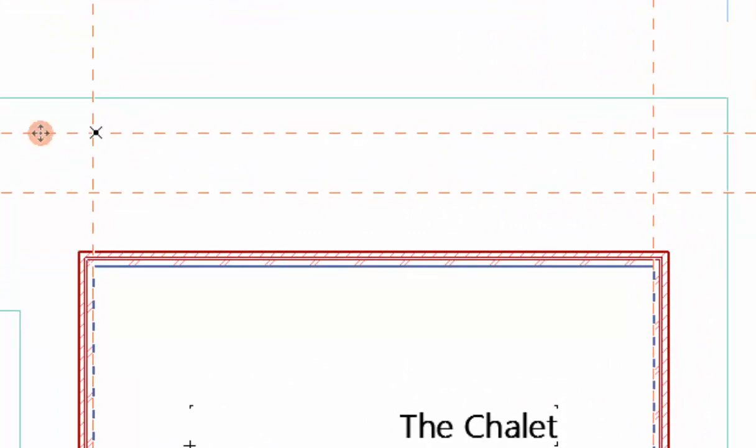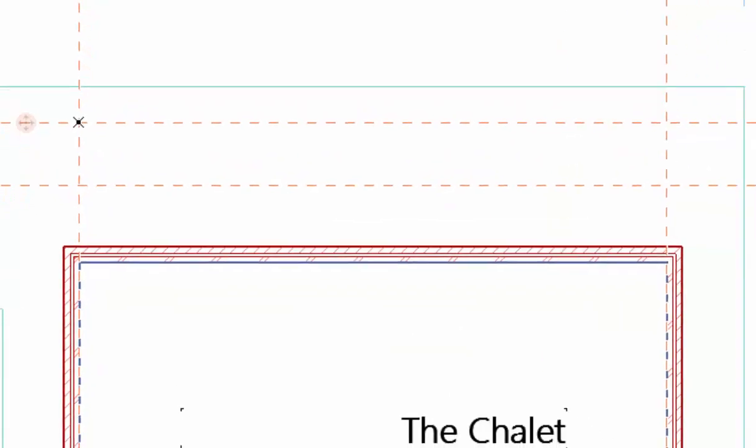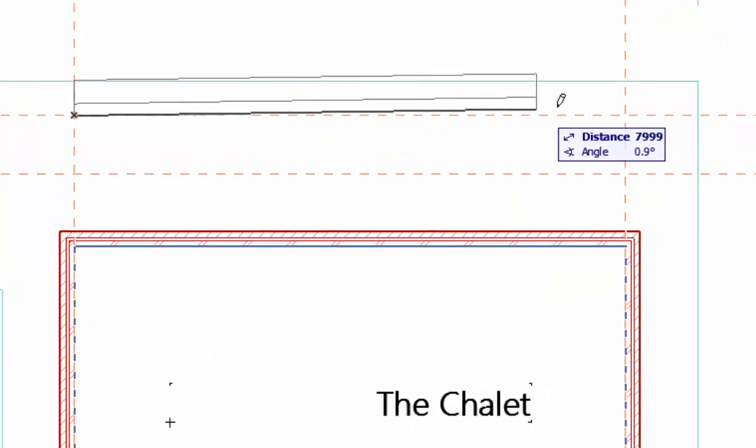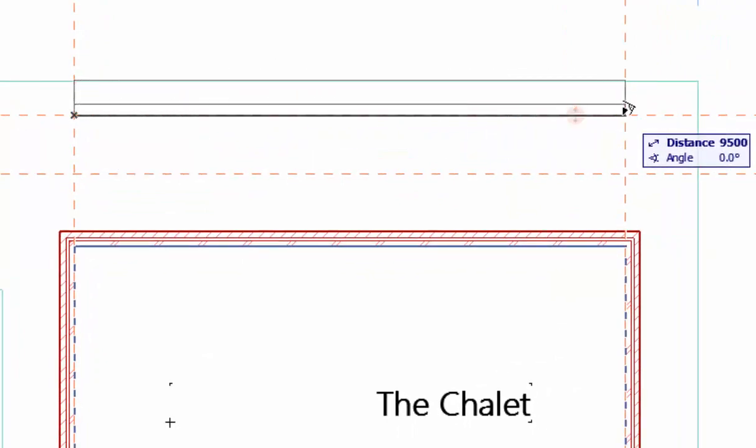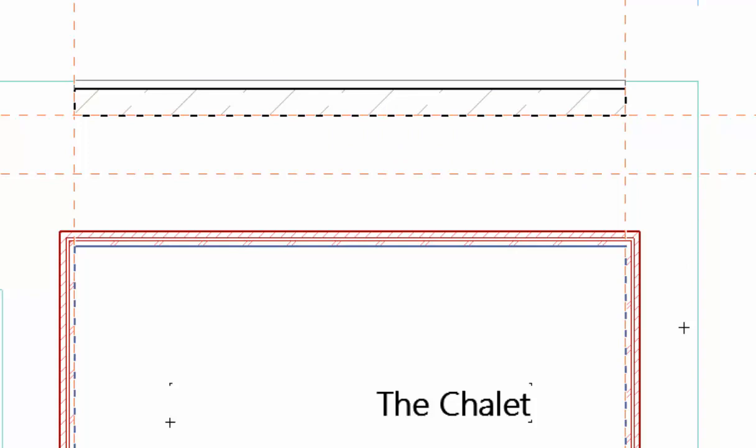That's our distance, and we're going to draw that in. So we've got wall selected. I'll zoom in a little bit. Just select that point here, pull it along, and it should snap to the other side. And there's our curved wall. Now we're going to move it down, this corner down 1 meter.